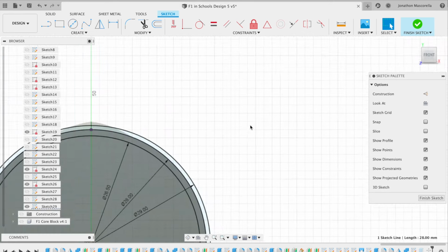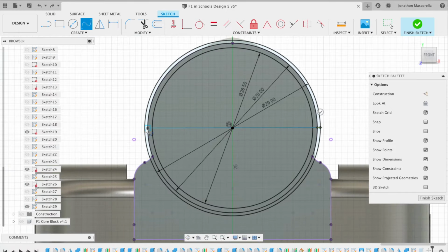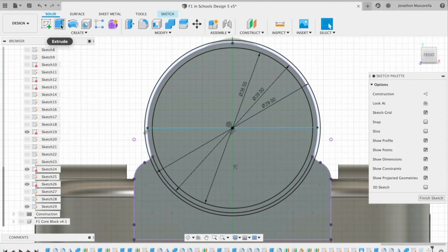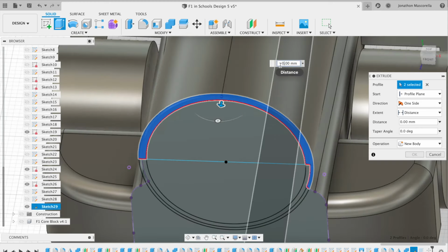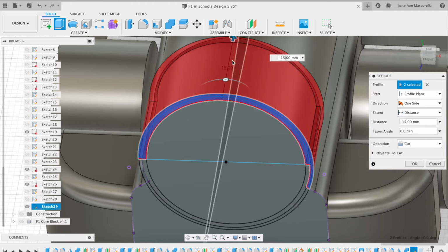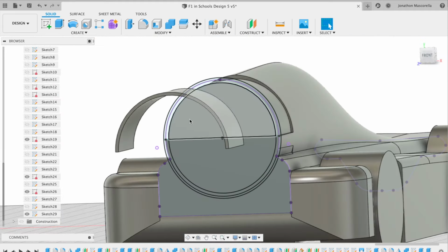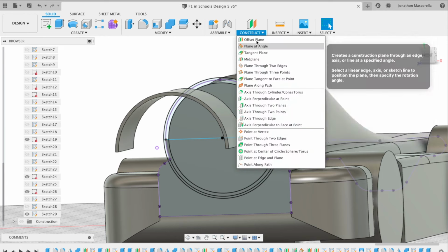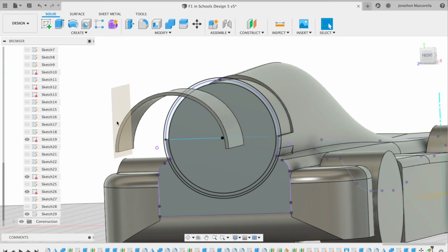You will need to do some finishing, and it's also critical to note here that when I designed at the very beginning of designing the car, I left 4mm of space around the outside of the CO2 canister, so that gives me enough room there to allow this to recess by 1mm into the back of the car. If you wanted to have 2mm, 3mm, 4mm, of course you would have to make the rear of the car a lot thicker to take up that space. Just be very aware of that before you go leaving exactly 3mm.